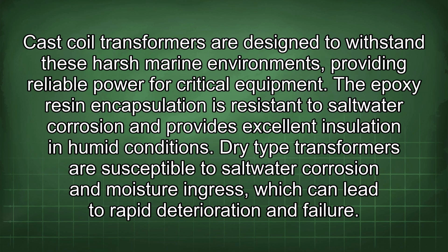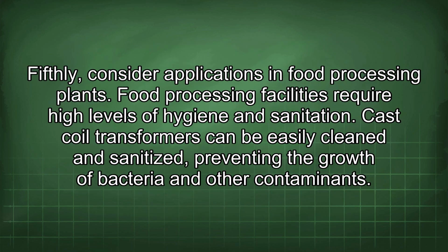The epoxy resin encapsulation is resistant to saltwater corrosion and provides excellent insulation in humid conditions. Dry-type transformers are susceptible to saltwater corrosion and moisture ingress, which can lead to rapid deterioration and failure. Fifthly, consider applications in food processing plants.